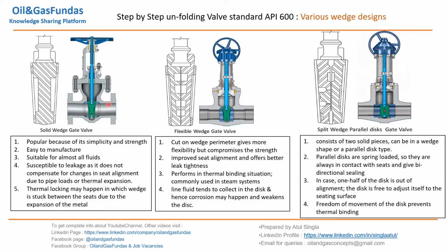It is very simple to manufacture, very strong and commonly used, suitable for all the fluids, but at thermal expansions it gets locked. It may get locked. So this is the only drawback we are having with this kind of wedge, which is solid wedge gate valves.